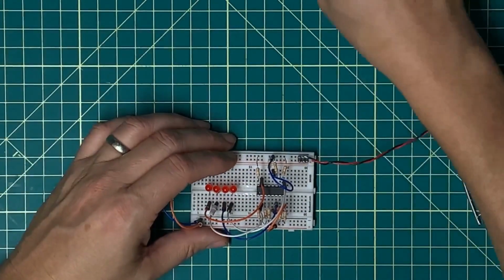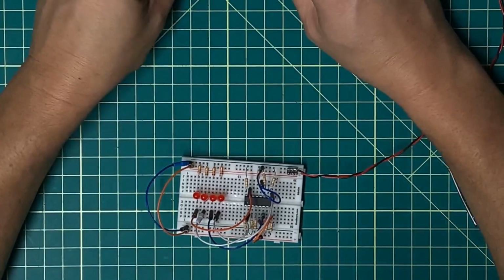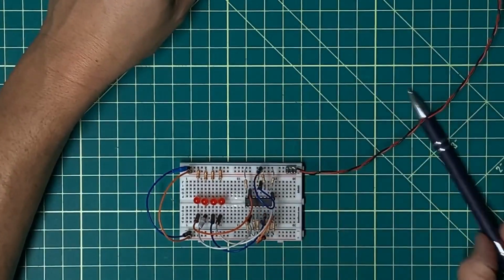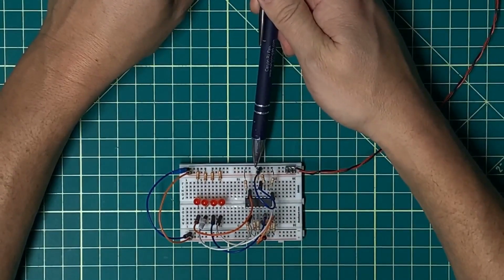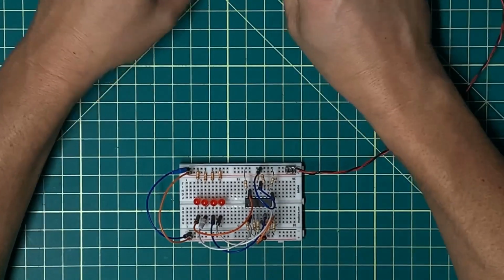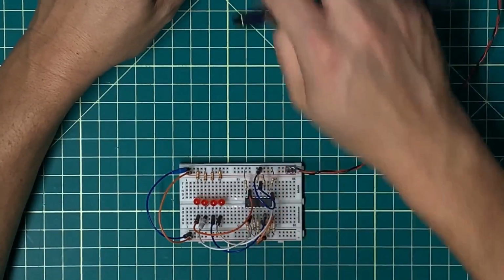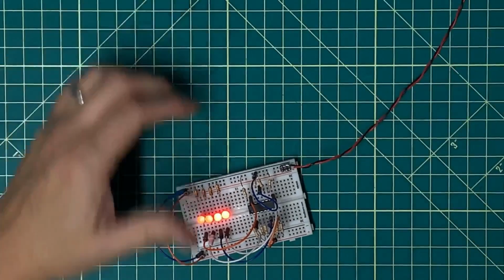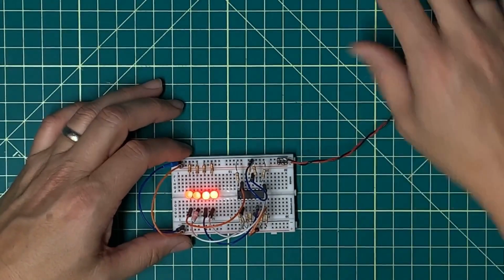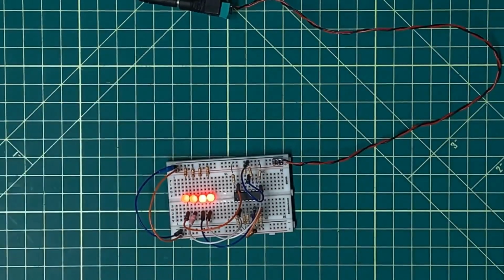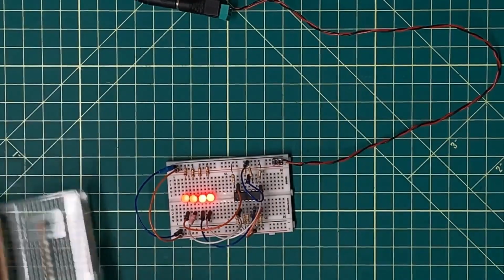output. This would be power, and when I power this up with all of my inputs, including my carry flag, tied low through 10,000 ohm resistors, my expectation is that all of these are going to remain off, and they do not. All right, so these are 10,000 ohm resistors.